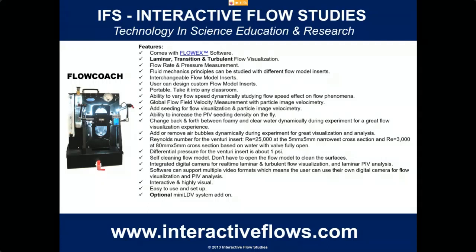Reynolds number for the Venturi insert is 25,000 at 5mm by 5mm at the narrowest cross section. I believe that's the Venturi. And Reynolds number is 3,000 at 80 by 5mm cross section based on water with valve fully open. You can measure the differential pressure for the Venturi insert, which is about 1 psi. Now it has the self-cleaning feature, so you don't have to open the model to clean the surface of the screen there. It self-cleans.